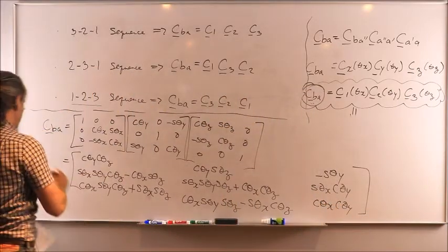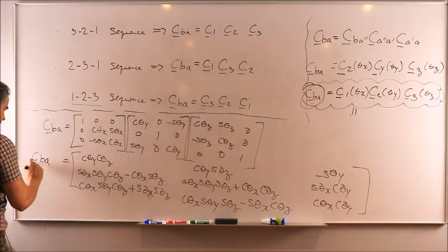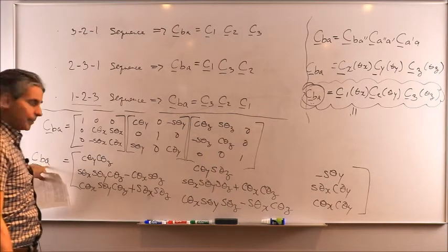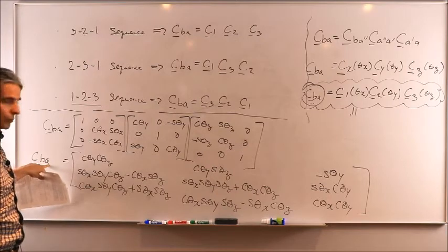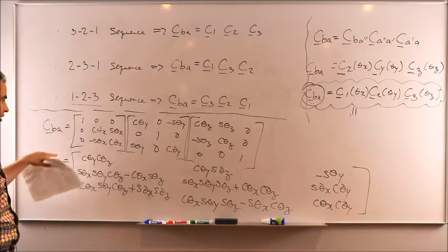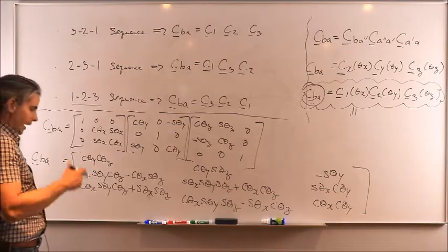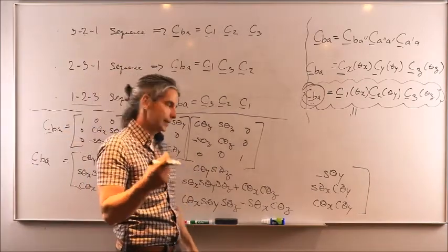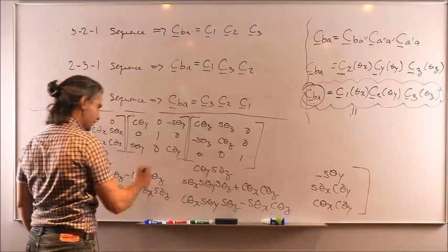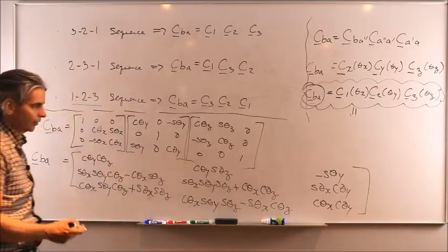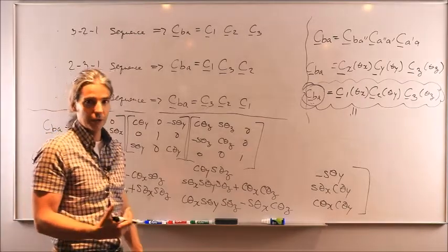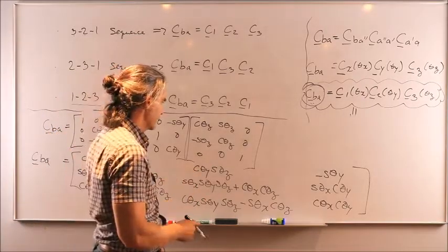To figure out the rotation matrix describing the orientation of reference frame B with respect to reference frame A, as long as you know the axis or the angle of rotation about X, Y, and Z, you just plug these angles in that matrix and you're going to get the answer for the 3x3 numerical matrix that allows you to do the calculations.